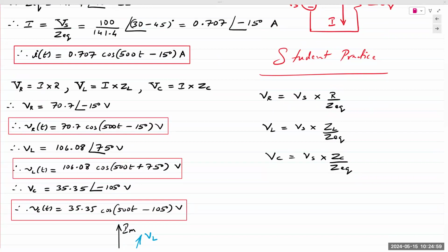Perform the inverse phasor transform, then you write out the function of current as a function of time, I of t. The frequency is not affected. Remember this entire chapter. Resistors, of course, behave the exact same way, so we don't have to worry about resistors. Inductors and capacitors affect the phase, they affect the magnitude, but they do not affect the frequency. The frequency remains exactly the same, which you obtain from the source. So 500 radians per second, omega stays the same.